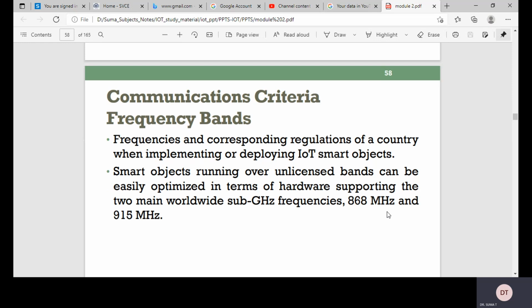Then IEEE 802.15.1 Bluetooth, IEEE 802.15.4 WPAN. The low range of Bluetooth limits usefulness in most IoT deployments. An unlicensed band, that is a band such as those in the ISM range of frequencies, is not unregulated. National and regional regulations exist for each of the allocated frequency bands, much as with a licensed band.